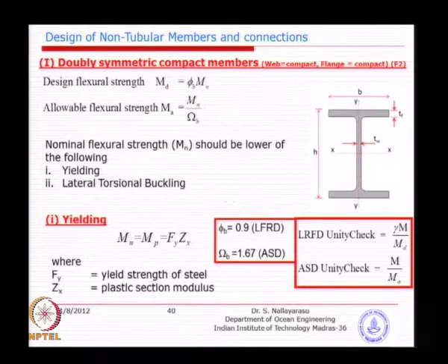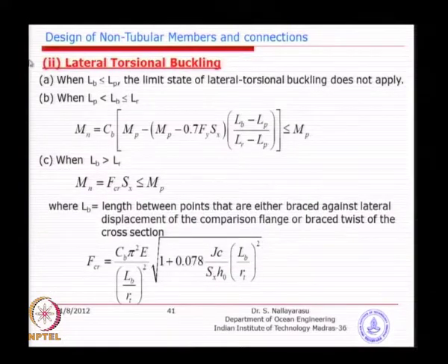So you go back here, you have full yield stress multiplied by plastic modulus, which is going to give you a very large moment capacity. When you make the section very small, or when you make the member longer, you see here the moment capacity is reduced by almost 30%. And in the last case, when it becomes too large, then you actually go into buckling, and also you have the modulus replaced from plastic to elastic.